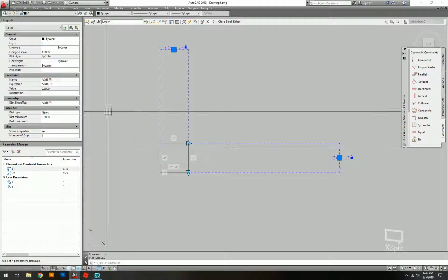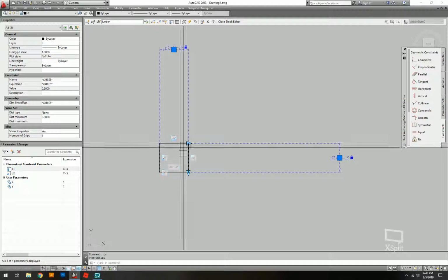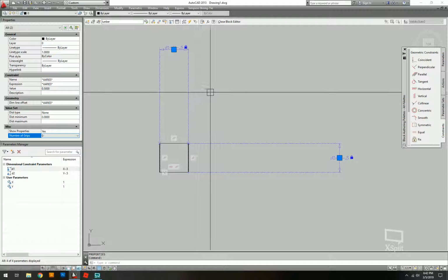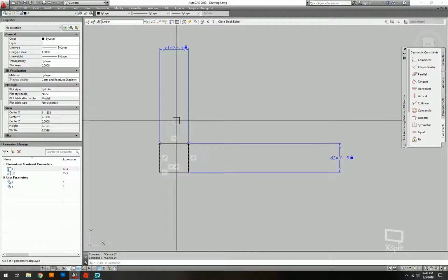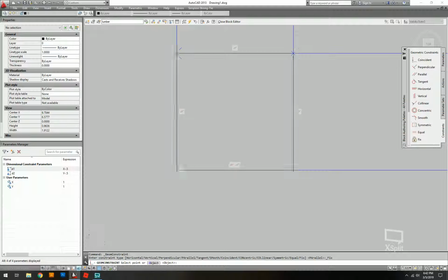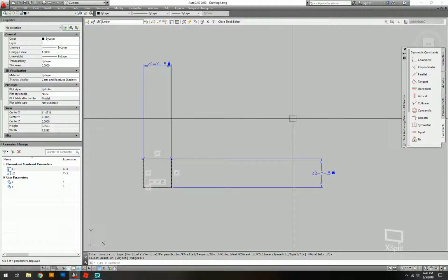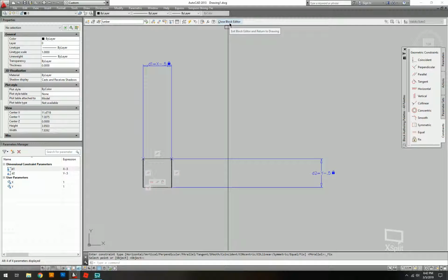There it is. Okay, so the number of grips is these blue arrows, and I don't want those to show up. Basically, we have these values, these expressions that we are going to be able to enter ourselves. So we're going to go ahead and put 0, and those two will disappear. Now, I believe that's it. We can go a step further and click the fix on the menu over here and just pick this corner, and that way whenever we enter a value, it expands up and to the right in the typical positive directions. So let's see if this worked properly.